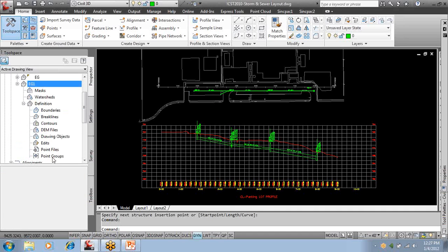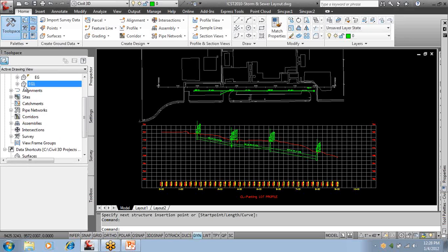So make sure you use these plus signs. Go add what you're creating the surface from, whether it's contours, a point group, other drawing objects, an XML file, or a DEM file. We have a lot of variety, but you have to make sure you add that data. As soon as you add that, the contours show up. You pick it and you start changing the different styles on how you want it to appear, and you can vary those styles as I did.